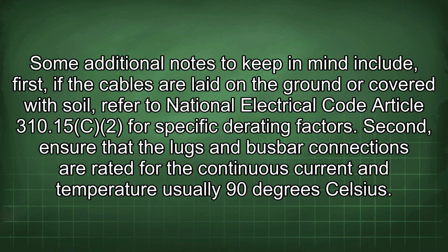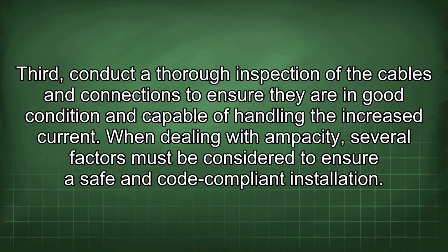soil, refer to National Electrical Code Article 310.15 C2 for specific derating factors. Second, ensure that the lugs and busbar connections are rated for the continuous current and temperature, usually 90 degrees Celsius. Third, conduct a thorough inspection of the cables and connections to ensure they are in good condition and capable of handling the increased current. When dealing with ampacity, several factors must be considered to ensure a safe and code-compliant installation.